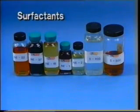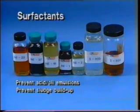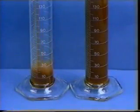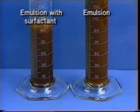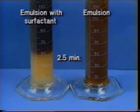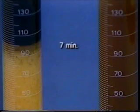Surfactants, another common additive, are used to prevent acid-oil emulsions, prevent sludge buildup, and change formation wettability. For example, the mixing of acid and crude oil often forms a thick, viscous emulsion that cannot flow through the reservoir. This impairs treatment fluid recovery. Emulsion testing before the acid treatment can help to identify the type of surfactant necessary to prevent the formation of stable emulsions. Though emulsions can still form, the surfactant will rapidly break them, and fluids can then be easily recovered.